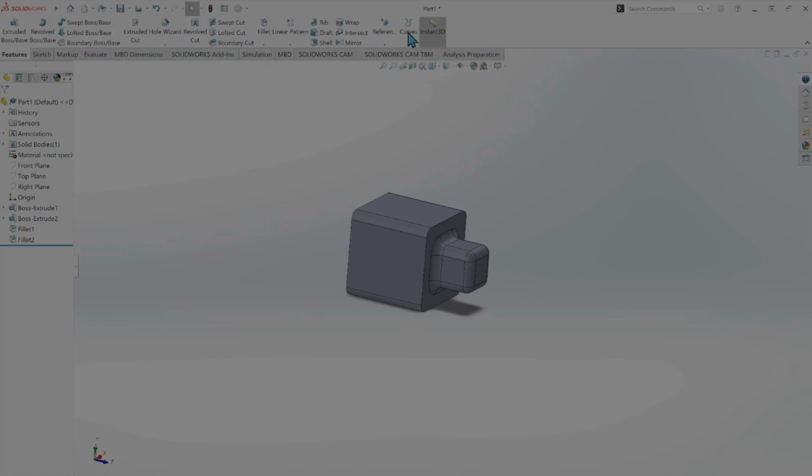At the very top of your screen will be your command window. That is where you get your features, your sketch features, your operation features. Then on your left is the feature manager, which contains the design tree, and it lists the structure of the parts, assembly, drawings, and the planes. Please make sure that you are working with the right units.